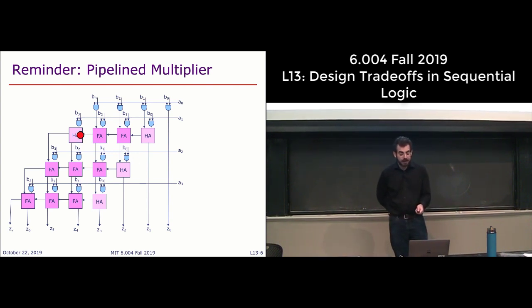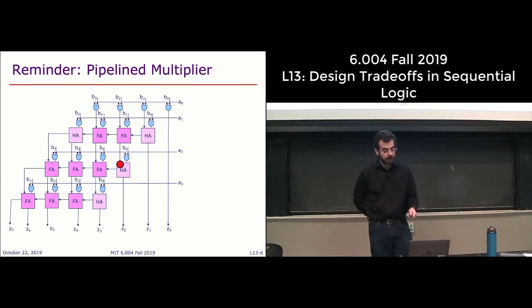And then each of these rows is adding up 2 of these partial products, right? And as we move down, we have n partial products. To add them all up, we have n minus 1 adders. So in this case, because we have 4-bit inputs, we have 3 4-bit adders, which we've gone ahead and run as ripple carry adders.